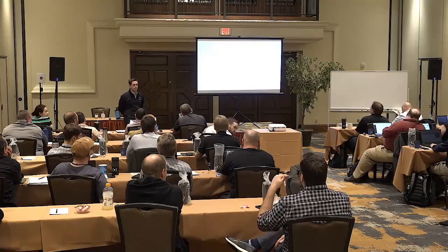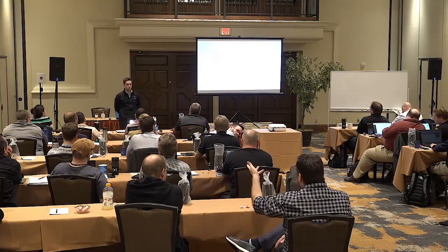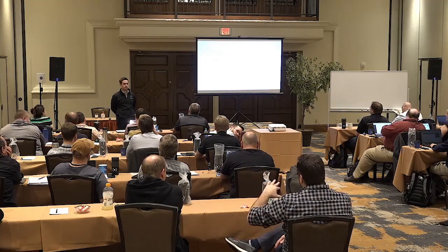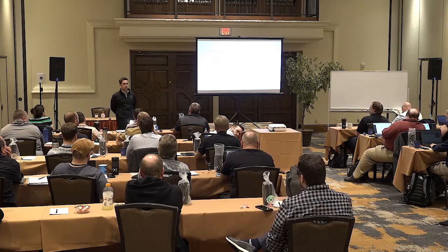Yeah, question? So when you deploy CBRS, you check in with the SAS, and it tells you what spectrum is available. Is that the same for low power equipment as it is for higher power? So the question is, when the radios in CBRS check in with the SAS for power levels, is that the same for low power and high power, category A and category B devices?